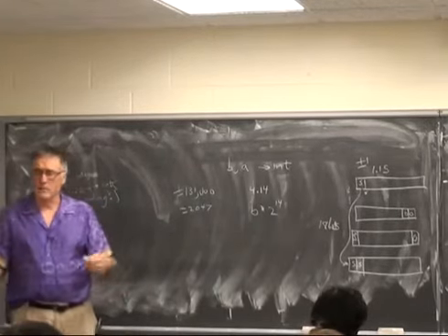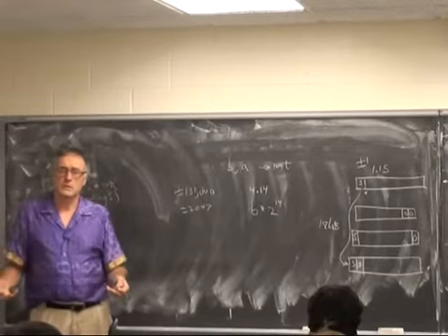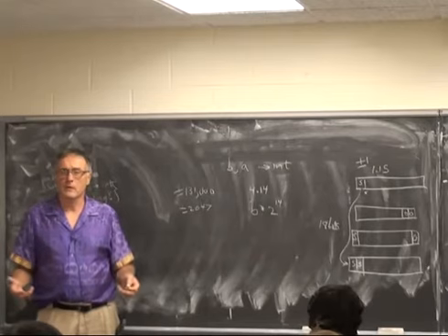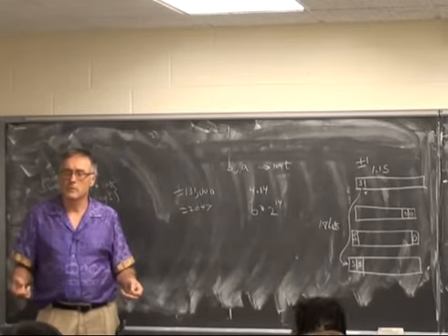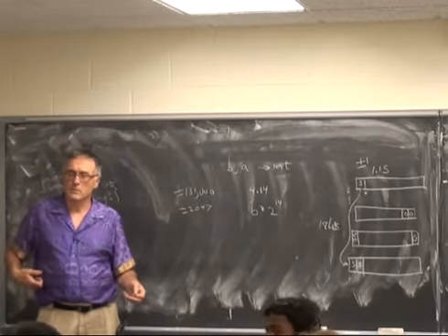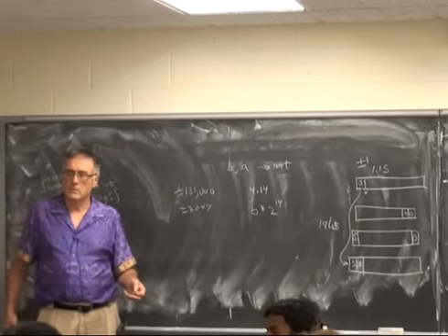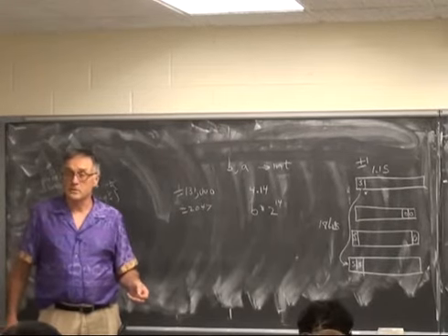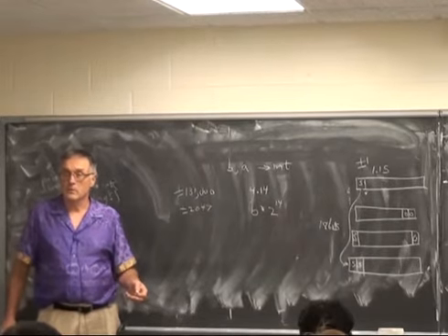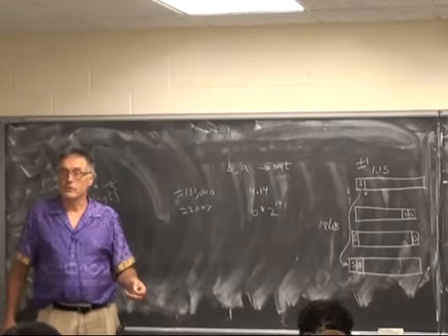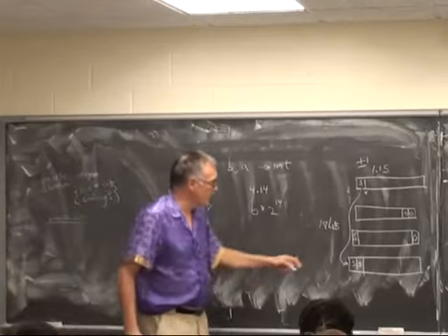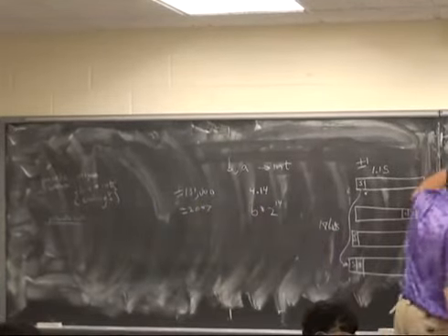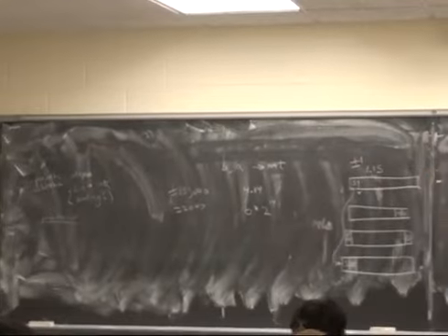Any questions about arithmetic systems? Since the signals from the codec are signed, does it automatically do the last one and just feed it in without doing it? No, you have to do the sign extension yourself. Even if the wire is signed? Even if the wire is signed. If you concatenate bits, because you're going to have to explicitly concatenate bits, right?